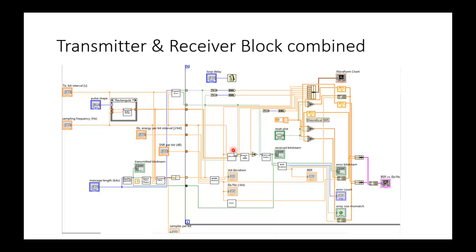The output of the correlator is then sampled and held, and then compared to a zero level threshold to convert the incoming signal to Boolean values of either 0 or 1. These bits are then stored onto the bitstream buffer. The regenerated signal that is stored in the bitstream buffer is then compared with the input bitstream in order to determine the error bitstream, the error count, the array size mismatch, and the bit error rate.